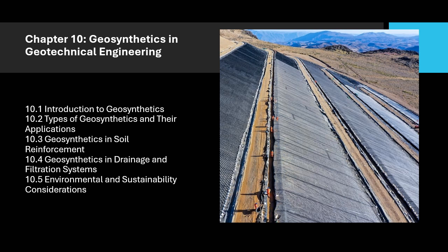Applications: 1. Landfill liners and covers. Geomembranes are widely used in landfill sites to contain hazardous or non-hazardous waste, preventing leachates from contaminating groundwater. 2. Water reservoirs and ponds. Used to line water storage facilities such as reservoirs, ponds, and canals to prevent water seepage.